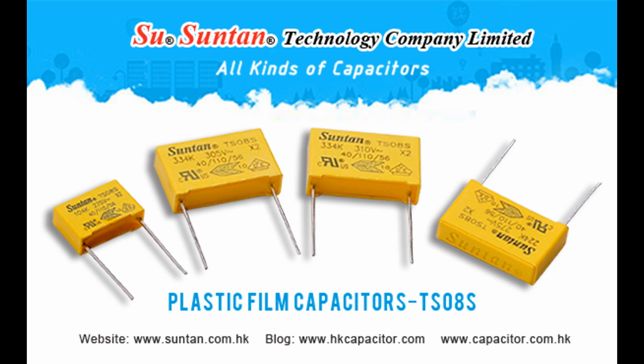rating. 2. Electrodes. Electrodes can either be metal foils (aluminum) or metallized films. In metallized film capacitors, a thin layer of metal (aluminum or zinc) is vacuum deposited directly onto the plastic film, which reduces the overall size of the capacitor. Foil capacitors use separate metal foil layers along with the dielectric, which provides better performance under high currents but makes the capacitor bulkier. 3. Winding of the film.